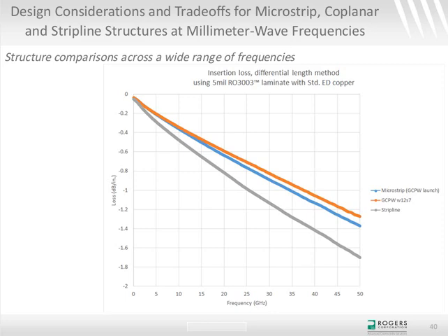So there's a bunch of different things to consider. I think as a general statement, microstrip usually has fewer variables that the circuit fabricator can alter. And grounded coplanar waveguide is a little more sensitive to the copper plating thickness and stripline thickness differences. That's kind of a quick overview of that, I guess.